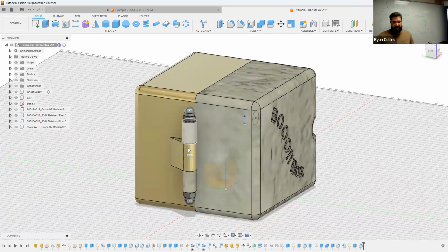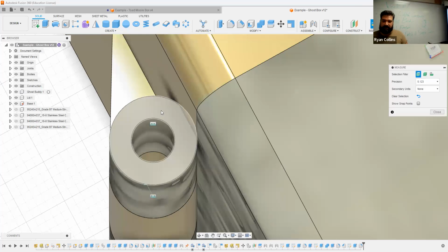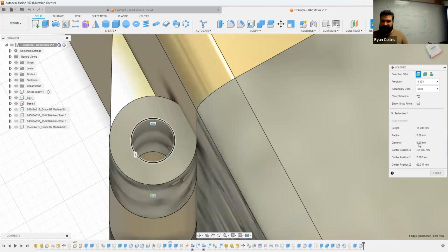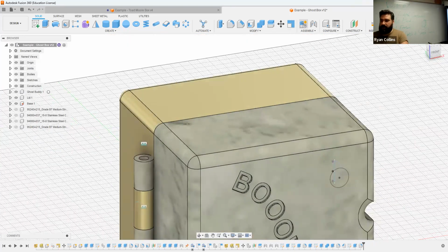Two options for this hinge here. Now, again, I don't know what happened to my sketch of my lobes. It's all messed up. But essentially, all I'm doing is I'm just going to hide these parts. And I just need to double check how big is that aperture. I can go to inspect that ring, go over diameter. It's a 5 millimeter hole. Cool. So what I can do, and I'm going to create a new component for this.